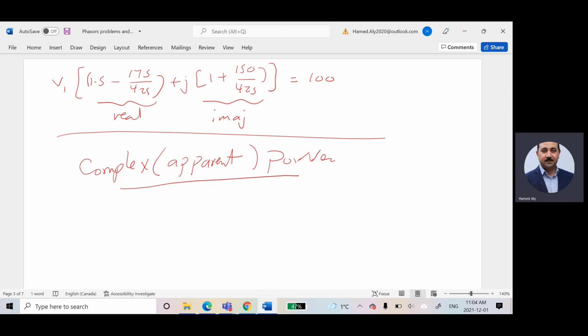So, if you would like to find the reactive power, or the imaginary part of the power, in the inductor, it's equal to the magnitude of I RMS squared multiplied by XL. What about the capacitor? Negative I squared multiplied by XC. So I can say the total imaginary part of the power is the magnitude of I RMS squared multiplied by XL minus XC. Am I right? If XL and XC are connected in series.